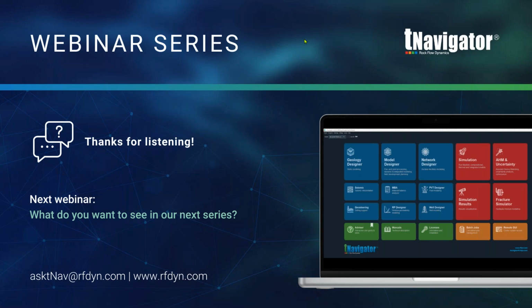Thanks. And I think the last question's for Serkan as well. So can tNavigator handle thermal simulation in cap rock too? Yes, thanks for that question. I see there's actually a few questions about the cap rock. So if there's anything specific you're asking that I'm missing here, please get back to us or write in the chat or send another question, because I'd like to follow this up. But as far as I know, the way we do the cap rock is actually the same as any other block, just has different properties. So therefore, once you have a thermal option, this is applied to the cap rock equally as it is done to the flow side, so to the reservoir. So yes.